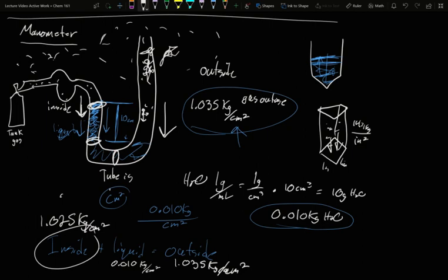This is how we actually go about measuring pressure changes, though. When you want to know whether you have less pressure inside or more by pushing the liquid up the other side of the container, you look at that height difference in your liquid, determine the pressure from the liquid, and say, well, if I'm no longer moving, my inside total and my outside total must be equal.